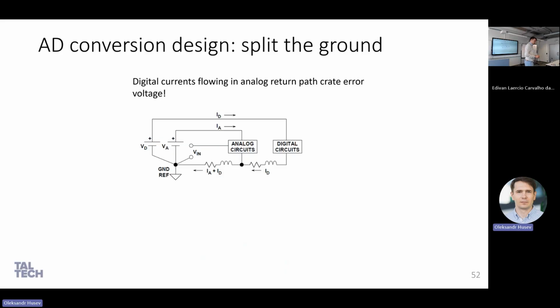But it just depends, because I understand why they may say this. They say that even if it's connected, it will still have a different path for digital and analog circuits. That's why, physically, they can be really connected, but you just need to always think about direct and return current in terms of digital and analog circuits. And if here you have a digital source, an analog source, right? And your digital source has a return path like this. This is direct and then return path.